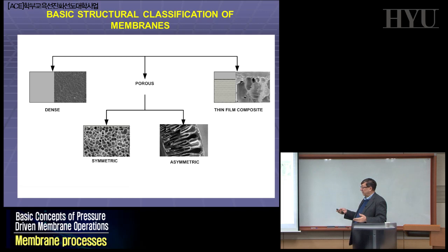The chemistry, the system is very different. The mechanism will be solubilization of one component in the dense phase and diffusion of the same component in this dense phase. Fick's law will be applied in one case, diffusion, and Henry's law will be applied in solubilization. So no pore. In the other case, when you're talking about porous, you will discuss in some cases about Poiseuille, viscous flow, convective flow across, Knudsen flow, depending on the size of the pore and the size of your particle going across. Very, very two different cases.